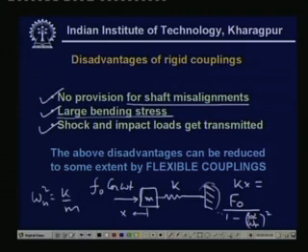where omega natural is the natural frequency and omega natural square is k by m. So, whenever we increase omega n, then this becomes very, very small. So, the entire force gets transmitted through this side, whereas if we have a small value of omega n, then of course, the total force transmitted will be very, very small.